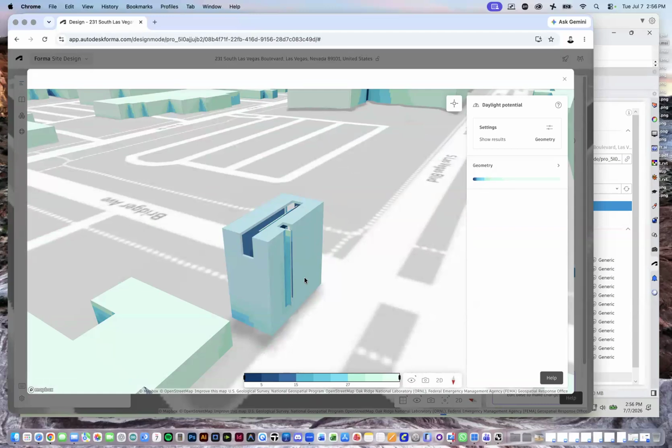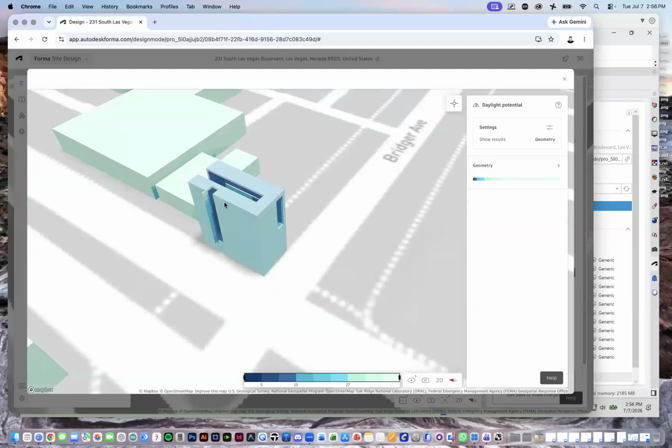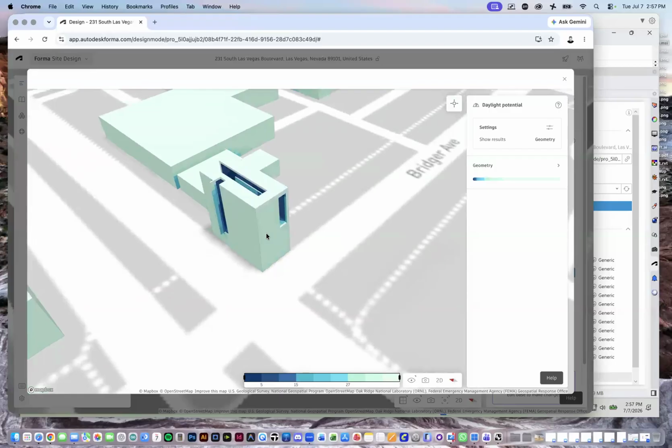But suffice to say that there's ample opportunities as long as you can bounce it, control it, separate the heat from the light, either through vertical baffles or horizontal louvers or deep inset windows or balconies or things like that. Again, thinking about your vocabulary of planes, how do you begin to work with that? You slide a plane outwards, or do you slide a plane over? You push a plane in, etc. You can begin to fine tune your light vessels now for the particular place and its climate.